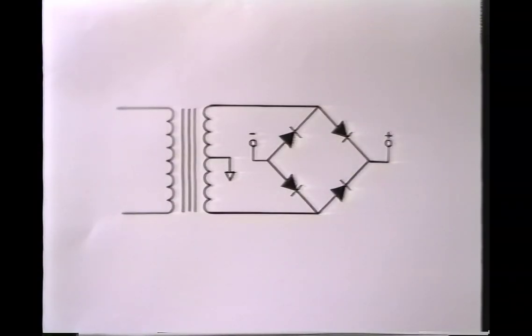This is a schematic diagram of the same split supply, but drawn in a different way. Does this look a bit more familiar to you? It's a bridge rectifier. Remember, you'll see bridge rectifiers drawn all kinds of different ways. In this case, the 2 diodes on the right are responsible for the positive power supply, and the 2 on the left for the negative power supply. Here's your clue for identifying a split power supply. Anytime you see a bridge rectifier powered by a center tap transformer, you're looking at a split supply.